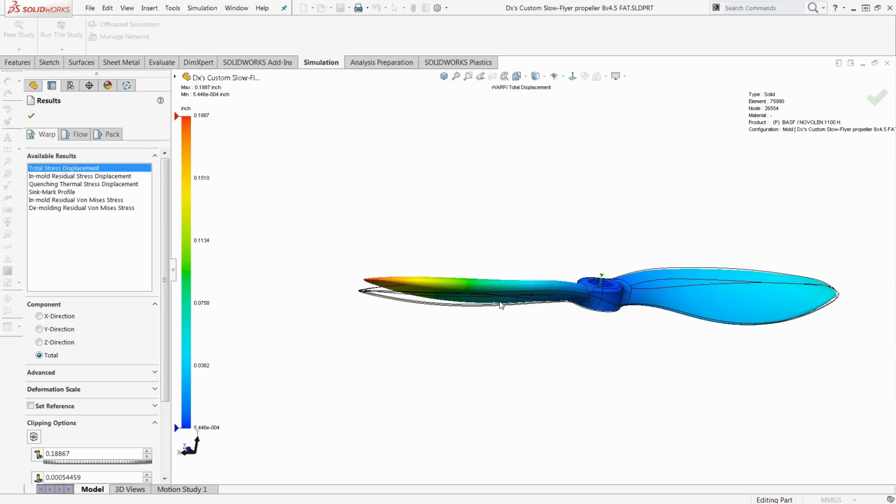Just wanted to hit on a couple of things more. One reason where 3D printing is useful is when you can test some of these issues beforehand. Also, something like SOLIDWORKS Plastics helps you export the warped shape itself so that you can test your designs on the warped shape, and you know if something will work or not based on the amount of warpage, and you can look at form, fit, and function of the warped shape itself.